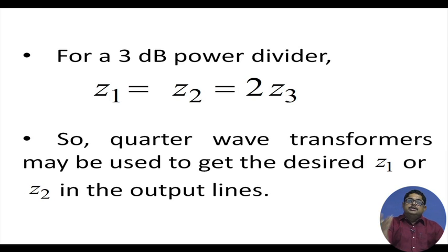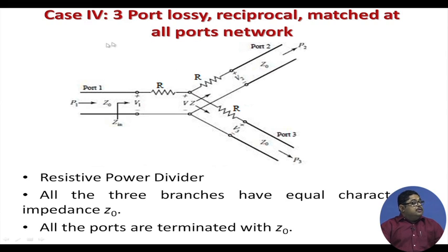Any impedance you can fabricate, but practically there may be some mechanical or fabrication difficulty, but theoretically you know how to make impedances. So, you can choose proper impedances that will give you the power divider. Now, there is another case left for that relaxed condition that we have not tried, the 3-port lossy reciprocal